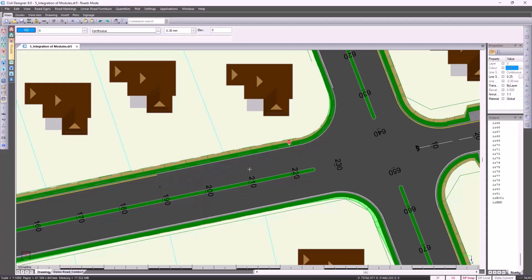While we are busy inserting these road signs and these road markings, we're working in a user-friendly 2D environment. Behind the scenes, Civil Designer is creating a 3D model for us, which I'll show you once we're done. Moving on to road markings, traverse markings. Let's put in a skew pedestrian crossing. You can go and customize these dimensions. Click on the start point, and then as you go and move your cursor, the marking would then update.